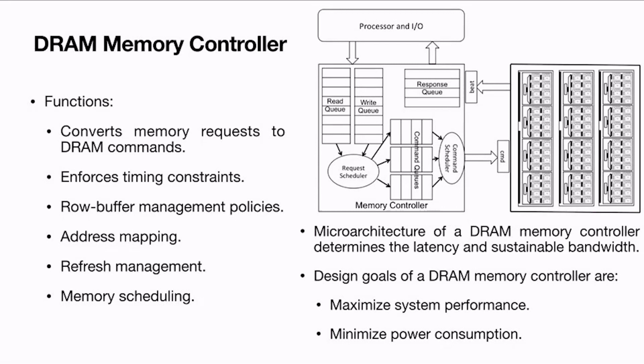Right now, we will be using DDR4 DRAM devices. Previously, there were DDR3, DDR3 low power, DDR2 and so on, and even DDR5 is there. You can go to the JEDEC website, jedec.org, and find all this information about new standards for DRAM memories, or the previous versions. Similarly, for GPUs, they consider GDDR technologies, the GDDR standard. So there are different designs, and different standards are defined for each of these memory components.